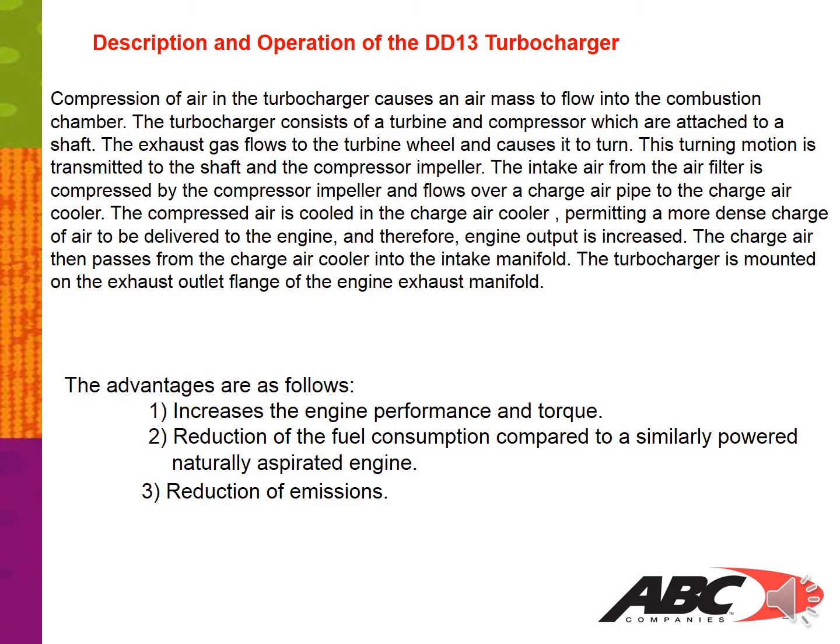The turbocharger is mounted on the exhaust outlet flange of the engine exhaust manifold. Some advantages are as follows: increases the engine performance and torque, reduction of the fuel consumption compared to a similarly powered naturally aspirated engine, and the reduction of emissions.